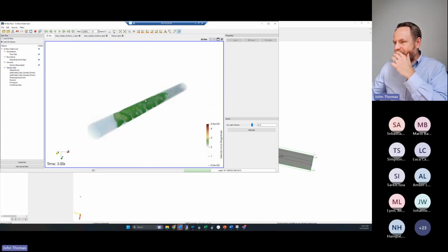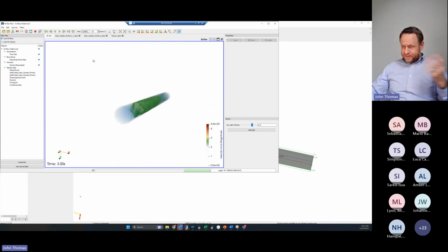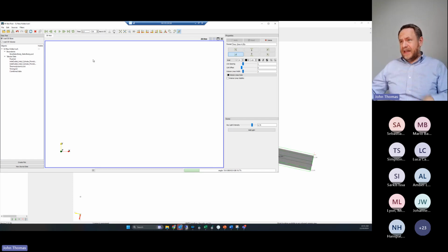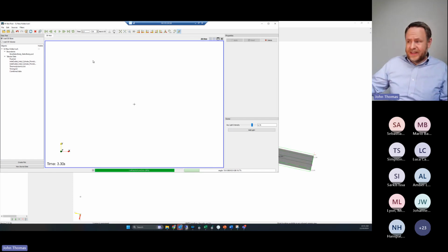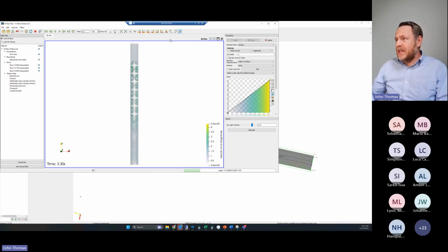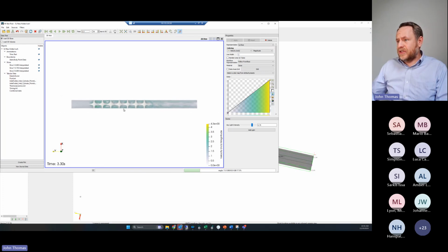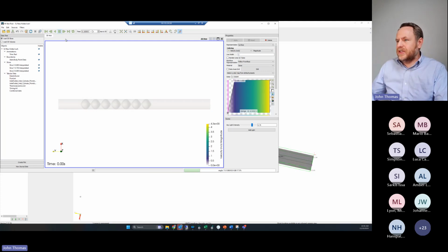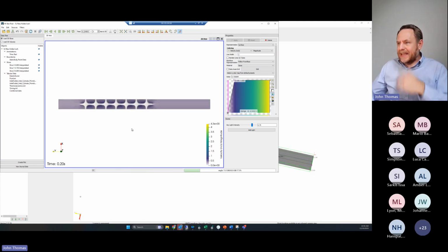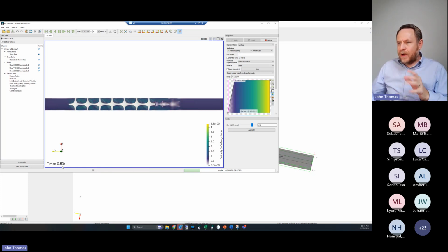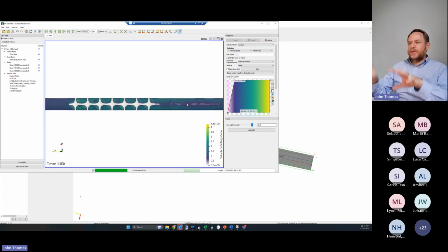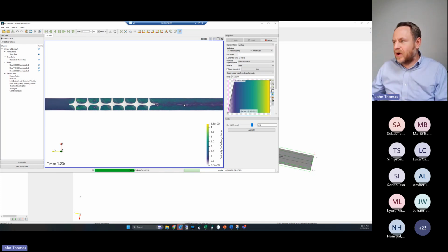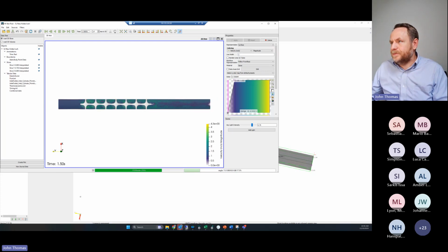Let me go over to my 2D slices, and you'll see it's an unremarkable pipe flow simulation, but nonetheless it's turbulent, right? Nonetheless it's got dissipation scales. Nonetheless, it's got a Kolmogorov scale, a Taylor scale, etc. As I watch this go, it's just turbulent flow, just having a good time. It's booting up here for the first second, and I get some turbulence downstream. This is looking at one cut plane through it. After 1 second, my ramp finished, and I'll see my turbulence downstream here as this low viscosity fluid goes through these turbulence-inducing elements, and I'll call them that to avoid any ambiguity.